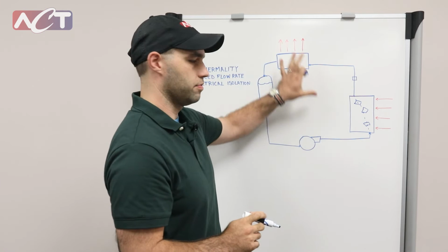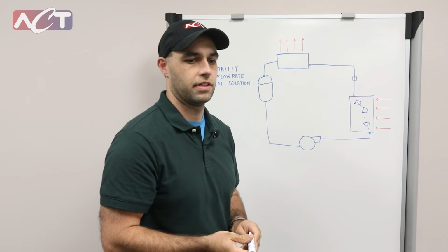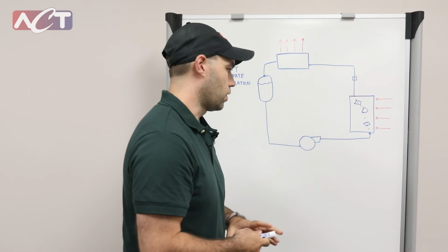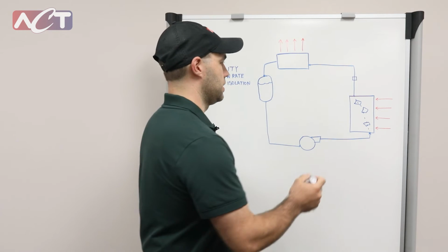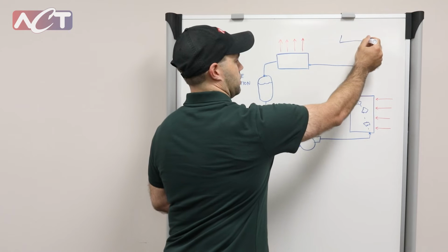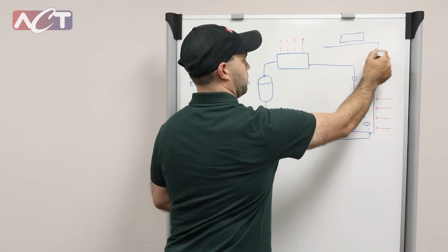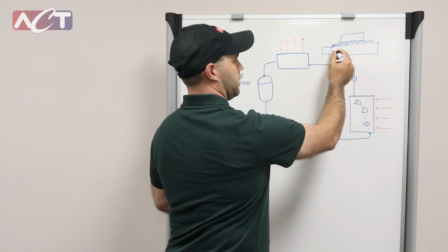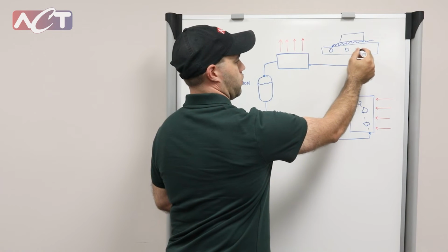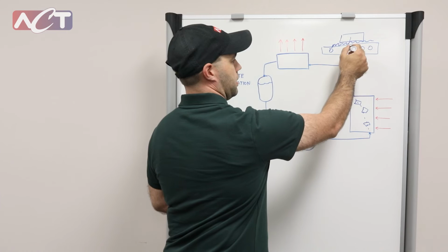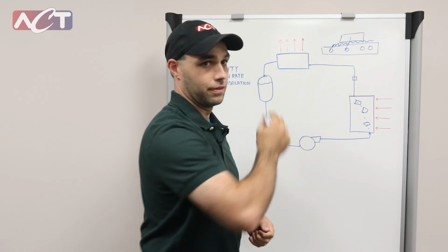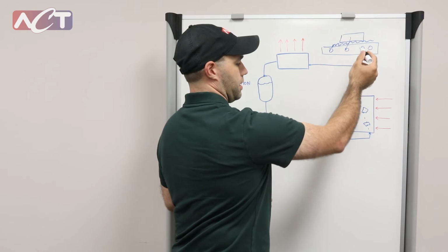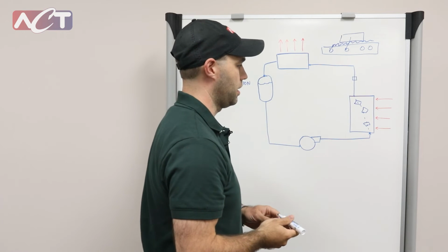And all of this stuff might be connected to frames or whatever that's grounded. And with a water loop, you would need to have your device attached to a cold plate, and you'd need to build in some sort of electrical isolation here. Otherwise, the water going through this is going to conduct electricity through the rest of your system. And so doing it on that scale can be challenging.